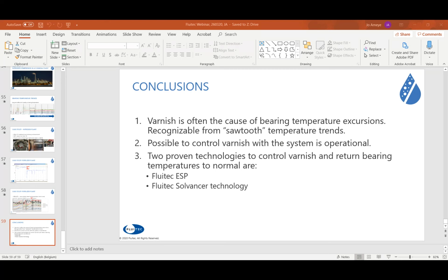If you treated with ESP and then after you bring it out of service your delta P starts to increase again, it's this very small, soluble amount of degradation products created by gas contamination. We've seen it on nitric acid plants, for example, and typically also with HCl gas compressors and ammonia compressors. It's very, very small, fine varnish, even at lower levels not detected by MPC. So if that is occurring, look at your particle size counting as well. It will give you the best indication that you're building up these first stages of soluble varnish.